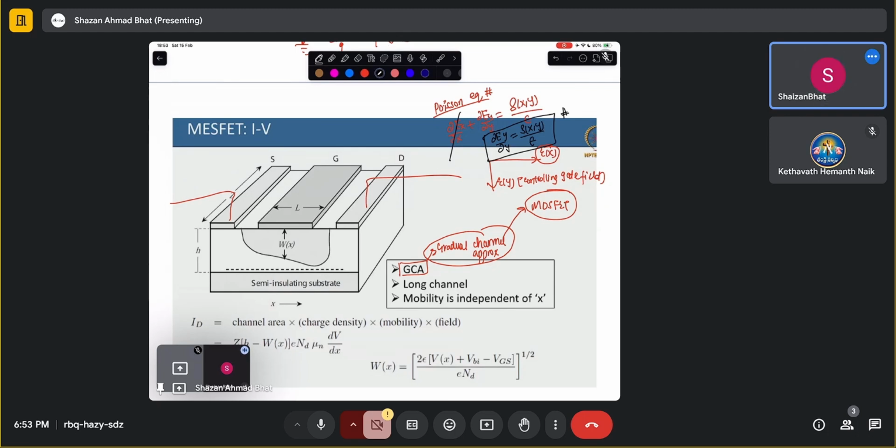So that is the long channel case. Now what will happen in the short channel? In the short channel, you see that these denominator factors can become appreciable, because this is ∂E over some dimension ∂x. If ∂x reduces, the overall factor increases. It's just a mathematical thing.